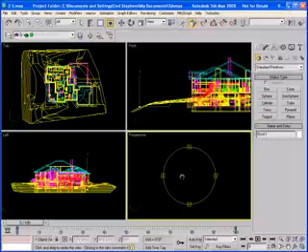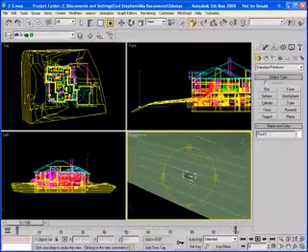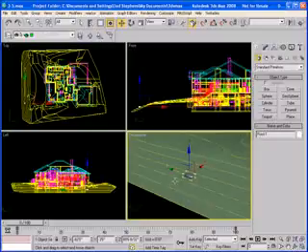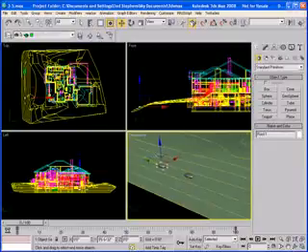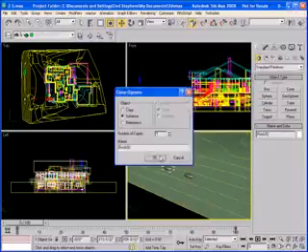And what I'm going to do is also clone this. I want to have several rocks in here, so I'll just clone it a few times. Use my arc rotate here to get it more into position. So I can go into my move command, and with move, all I've got to do is hold down shift and then move along one of your axes, and that's going to clone the object.